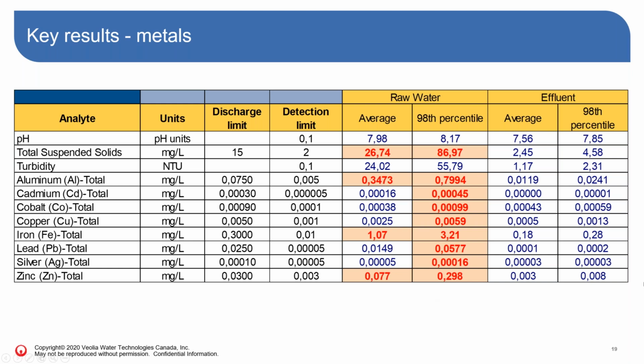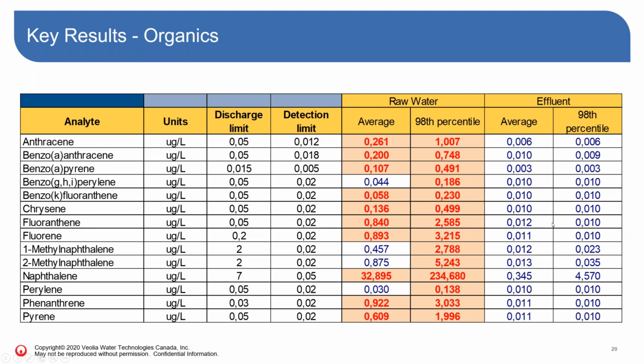Metals were not the main contaminant on that site. Organics are, especially with the coal gasification industry that was on site earlier. Those are all PAHs. There are more in that group, but I selected the ones where we had the most exceedances. So you can see that the raw water exceeds all of those parameters. Again, you see that we have excellent results in the treated water. We are removing, again, about two orders of magnitude for the contaminants.